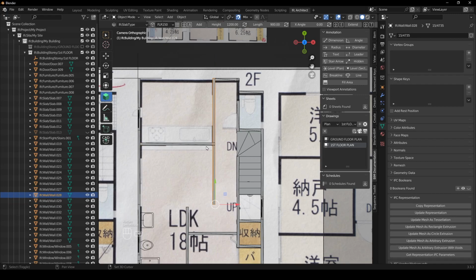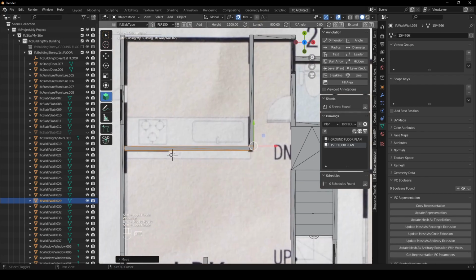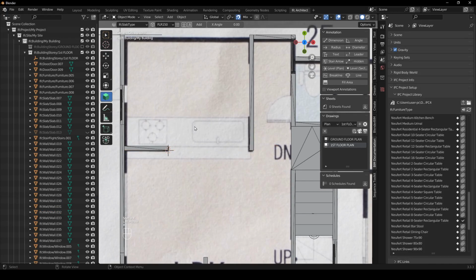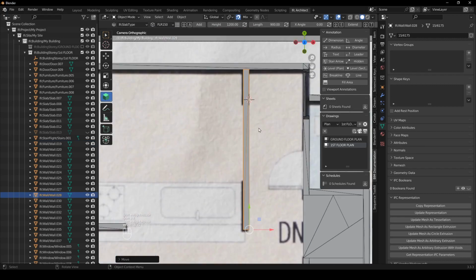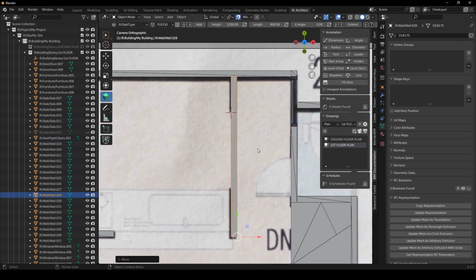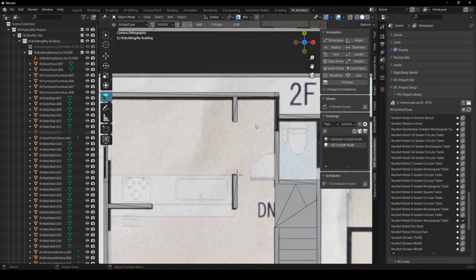And then take this guy and snap him to there, Shift E. I'm going to cut this guy in line with this floor, Shift K, and then delete this extra wall. These two I'm going to snap together, Shift T, and then him I can say Shift E there, and then I'm going to cut it where the walls are showing. So Shift K, and over there, Shift K. And then I'm going to delete this inner wall.